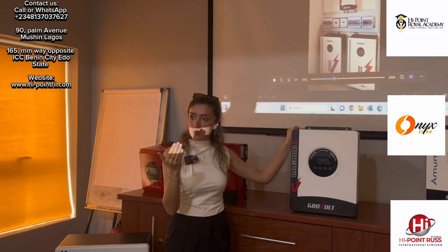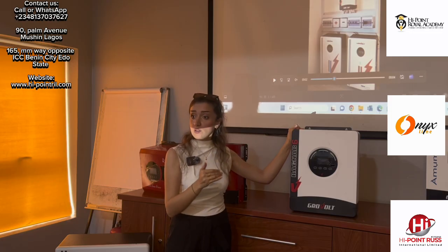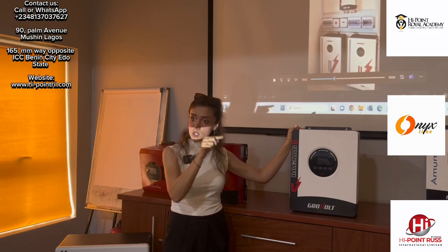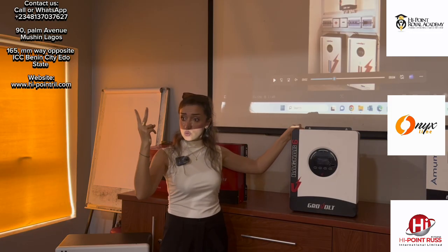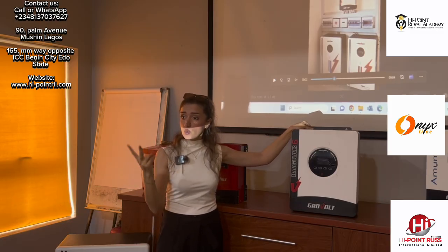Setting 1 is for the type of the battery. You will choose lithium or flooded or AGM. You will choose your battery. The second one is for BMS, it's 0 or 1. We have two values for the BMS protocol, 0 or 1.